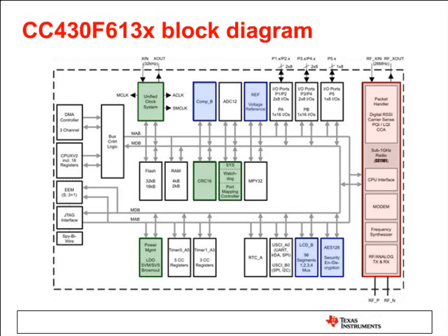kilohertz signals, right? And your low power modes, how the 430 and the CC430 really achieve extremely low power is by turning off these clocks in succession. And so in the LPM3 mode, you have your A clock or all your slow peripherals enabled, and you can actually operate this down in the 2 microamp range and have an active real-time clock. Any slow peripheral, you can have some serial communication at lower speeds, maybe 9600 BPS. But there's a lot of functionality still in LPM3, and a lot of that's based on the unified clock system.